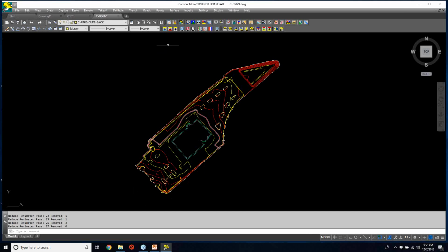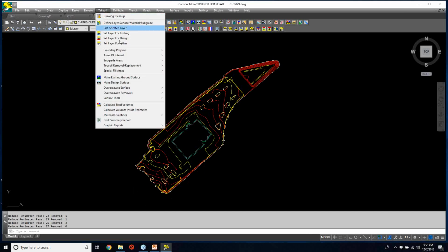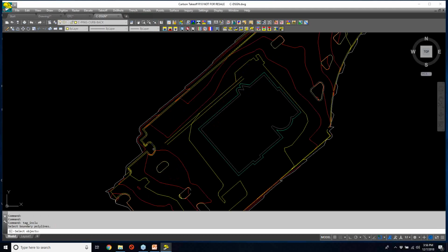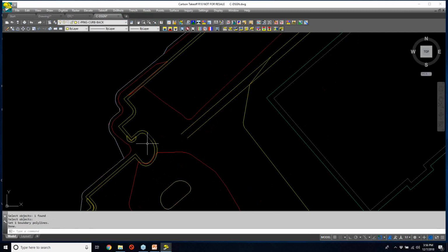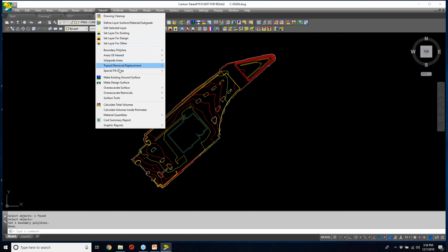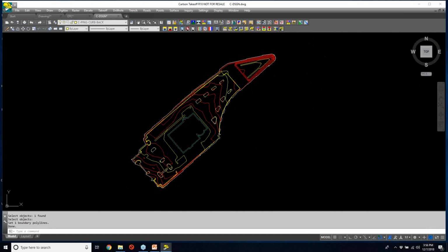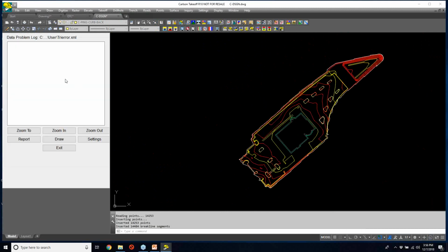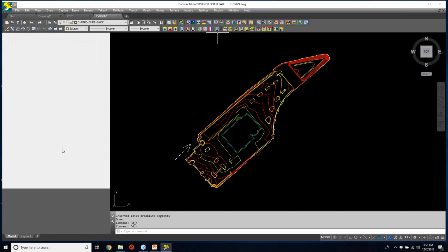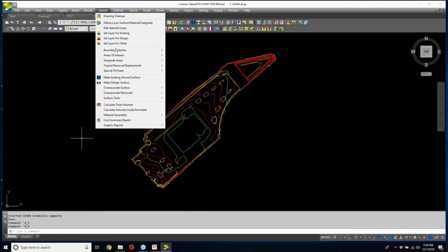With that boundary drawn in, I'm going to say takeoff. Set the boundary polyline. We will pick up that boundary polyline right there. And we will now make existing, which will be done. So we're going to gather up all the entities. We had a few little, again, minor little errors that are just outside of the site, which is okay, not too worried about it. I'm going to go ahead and choose then Takeoff and make design.